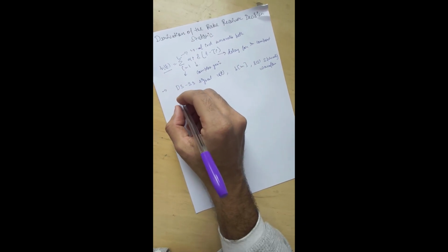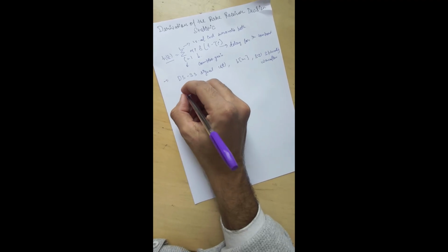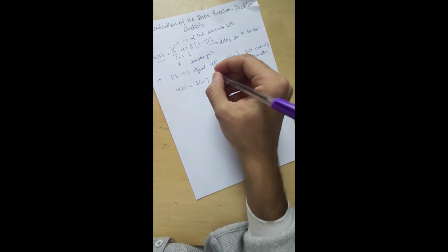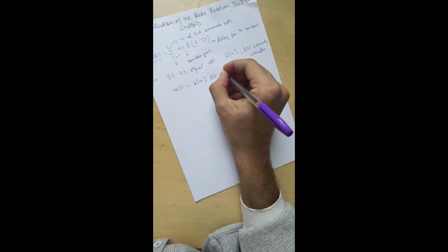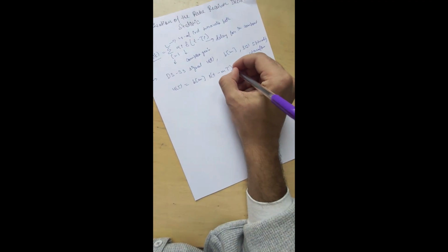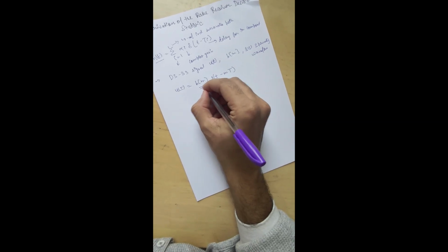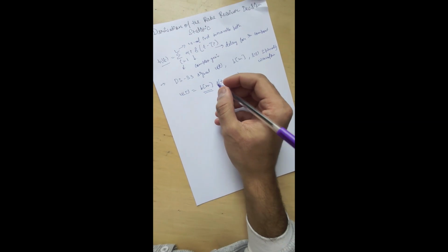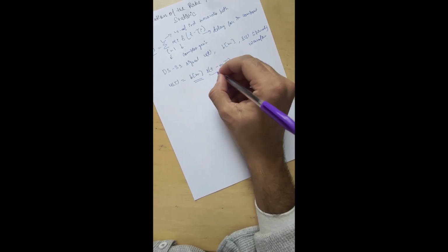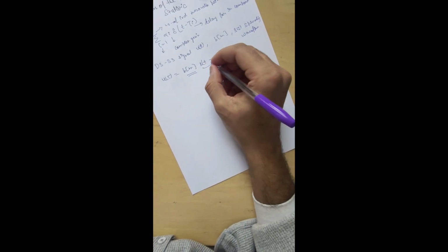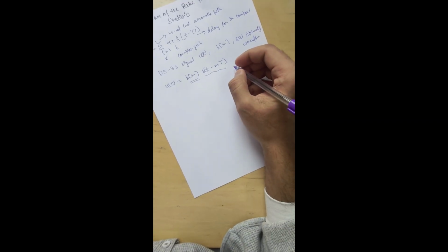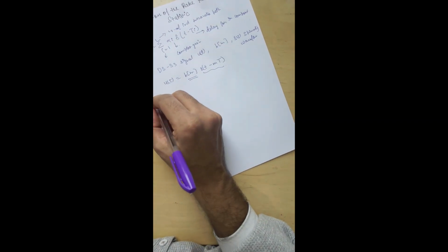So the direct sequence spread spectrum signal u(t) is given by this. And again, b_m is a single symbol, the mth symbol, and s(t) is a spreading waveform here delayed by the time period capital T.